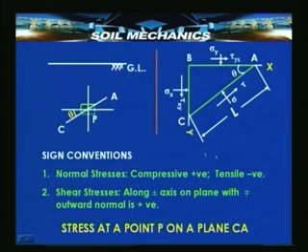So, also tau xy. Now, with this we will be in a position to calculate the stress on any arbitrary plane CA, provided we know the stresses on AB and BC. Usually they are known because, for example, take the plane AB, that is horizontal. The stress there is essentially due to the weight of the column of soil above it, and the stress on the vertical plane is a fraction of that, depending upon what is known as the coefficient of lateral earth pressure, about which you must have definitely studied in some other lecture.